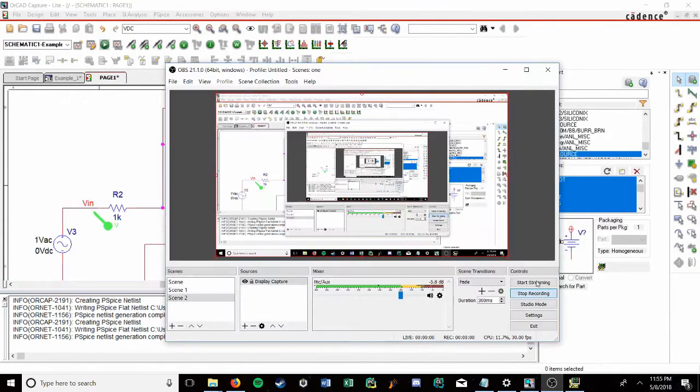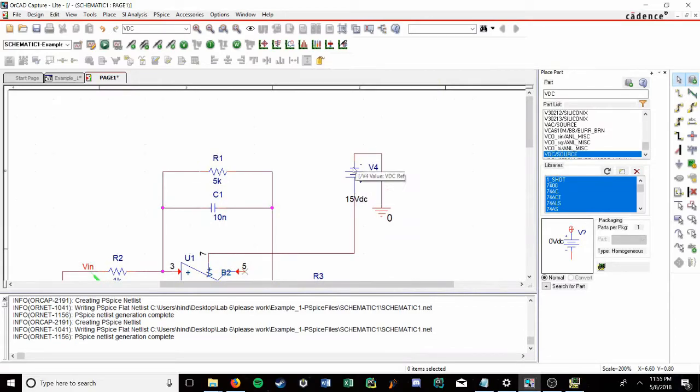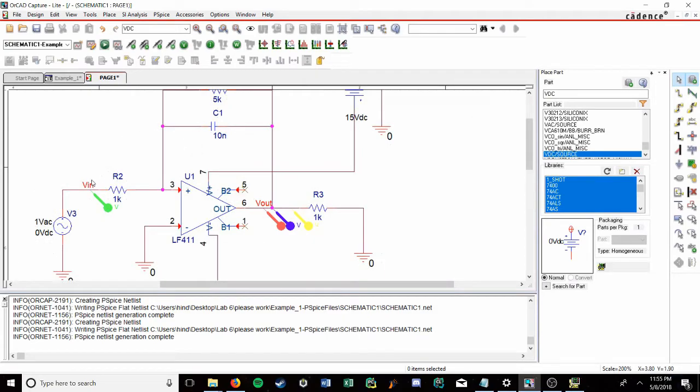Okay, I'm back. Anyways, sorry about that. I had a quick mistake. I had my voltage source in the wrong position, so I quickly flipped that around. And then what you want to do is put your clips in. They'll come in as black. You want to put one at Vin, one at Vout. I put 3 here because for some reason, when I graph mine, it doesn't work unless I do 3.